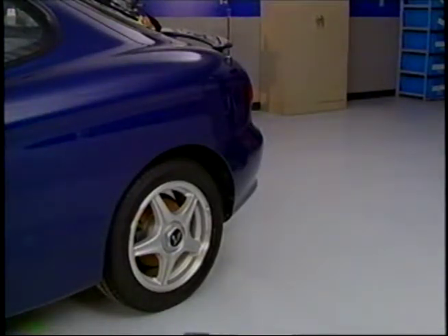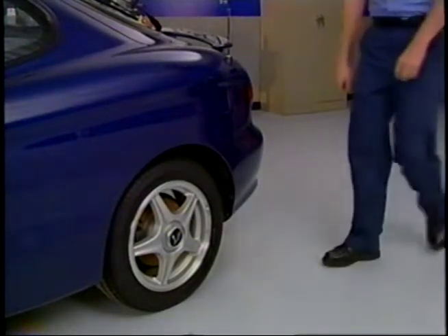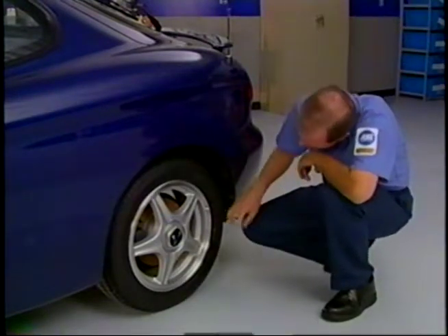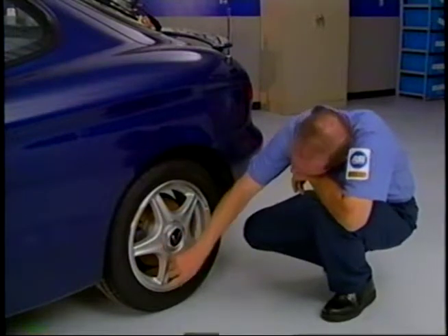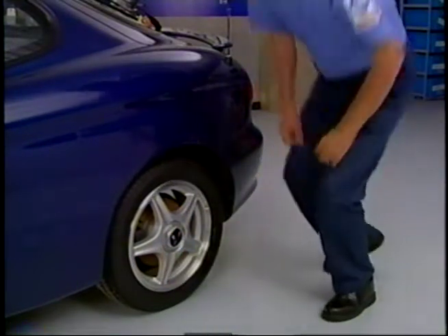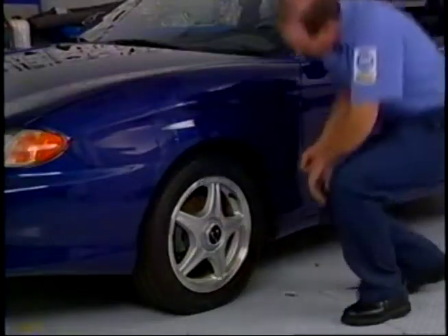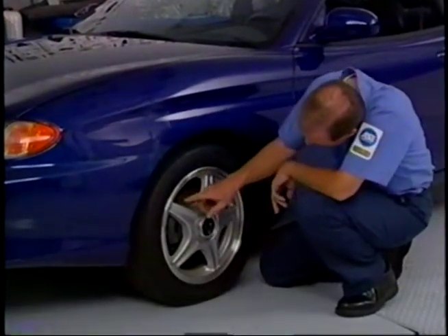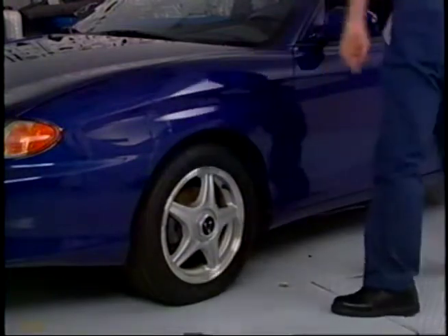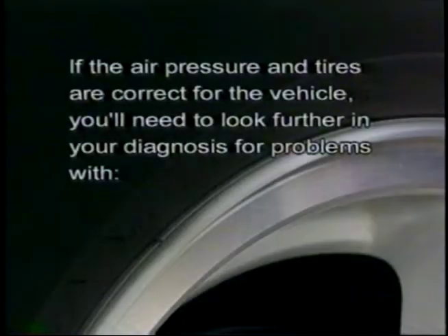the vehicle to wander. If the tires are properly inflated, continue your diagnosis by looking for mismatched or incorrect tire sizes or types that can cause similar handling problems. Use the DOT numbers and tire specifications stamped into the sidewall of the tire to confirm the proper application and load rating of the tires. If the air pressure and tires are correct for the vehicle, you'll need to look further in your diagnosis for